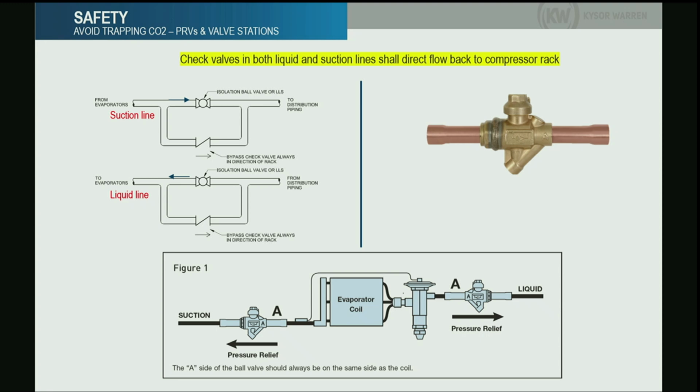Those valves over here, there is a limitation on sizes, basically. Those go from 3/8 up to 1 1/8 sizes. But those valves are rated for 1,300 psi. So you can use them easily in many parts of the systems.